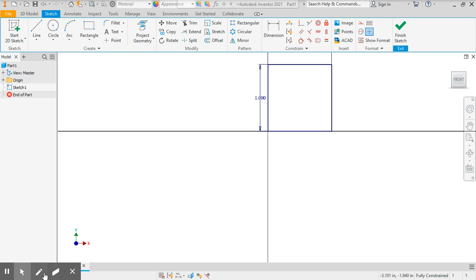Oh, I think this is in here because I'm using Screencastify, but that's covering up my status bar. If I pick my rectangle tool, it's going to say pick beginning point, pick other point or ending point of the rectangle. So I'm just dragging my mouse out. After I let go of the mouse button, I can key in the size of my rectangle.